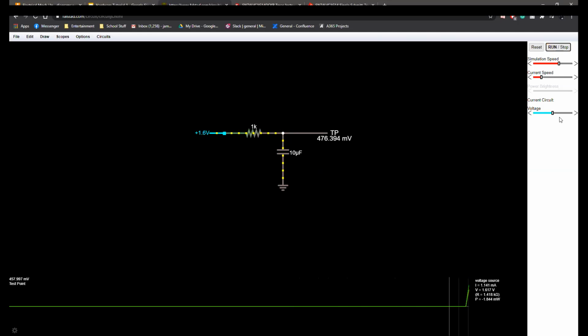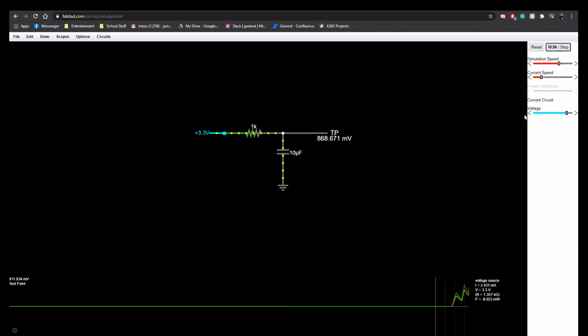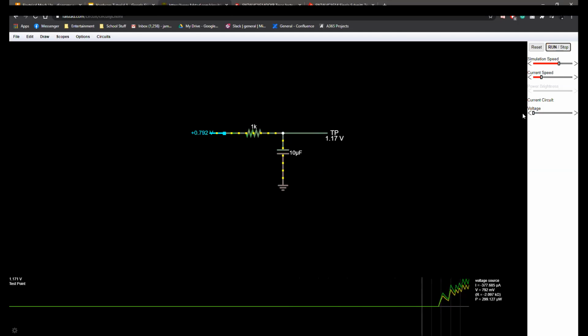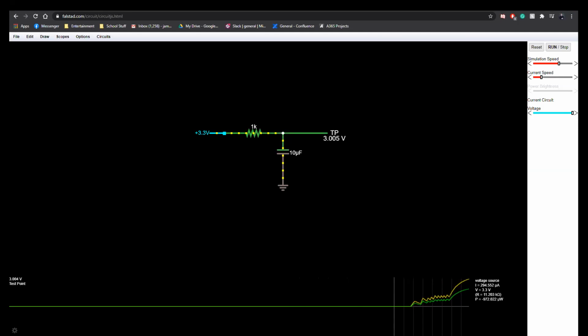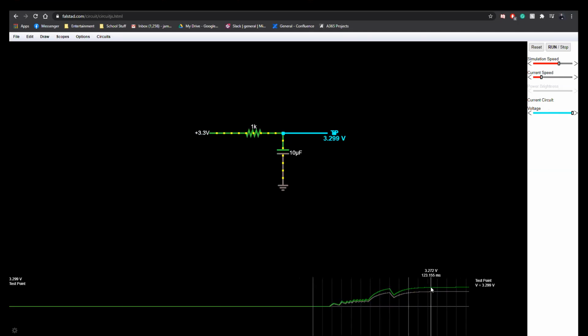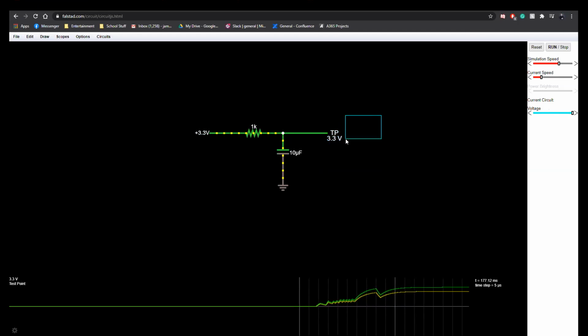When I go high and then low, high and then low, and then I can go high and low over and over again, and then eventually it should rest at high. Please stay there. Okay. You see all the bouncing, none of it ever actually reaches the 3.3 volts because of the capacitor. It takes time for the output to hit 3.3 volts.